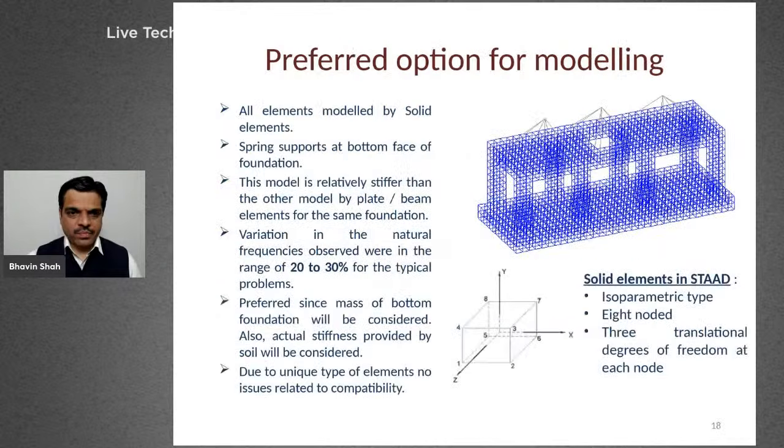So with this, now we can summarize the preferred option for modeling. In my opinion, all elements for this kind of foundation can be modeled using solid elements, and spring supports at the bottom face of the foundation. And this model is relatively stiffer than the other models by plate/beam elements for the same foundation, as we just discussed. And variation in the natural frequencies observed were in the range of 20 to 30% for the problems for which I made the comparison.